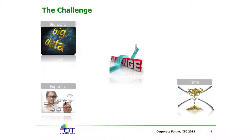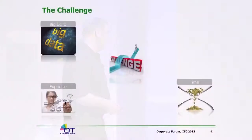And how do you know what kind of issues are occurring typically in chips, possibly generally in the industry, to know where you need to focus your attention? Another area is time. Craig talked about this a lot. It's one of the big advantages of working with OptimalTest. Data logs arriving after 2, 3, 4 days are typically too late for you to be able to handle any kind of escape prevention. For example, if we determine that there's something wrong on a tester and you know about it a day after it happened, if that wafer has already gone on to the next stage or even worse, gone on to assembly, it's too late. You can't do anything to stop that part from being shipped.